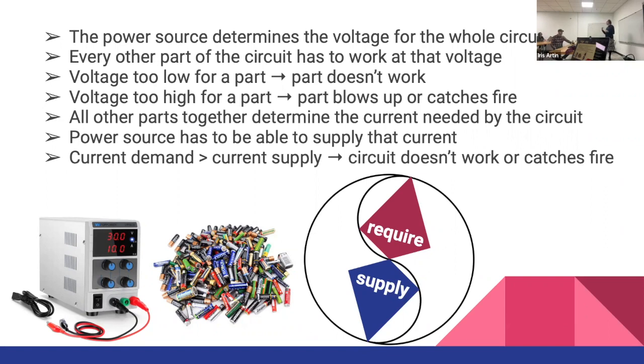So, for example, if your circuit just has a couple of LEDs in it, you might see that they are flickering, or that one of them is on and the other one is off when both of them should be on. If you have a circuit that is supposed to do some kind of blinking light, they might be working too slow, or they might be intermittently flickering and some of them just turning off. Any kind of deeply mysterious, I-don't-understand-why-anything-would-ever-behave-this-way behavior is a potential consequence of either voltage too low or current just borderline.